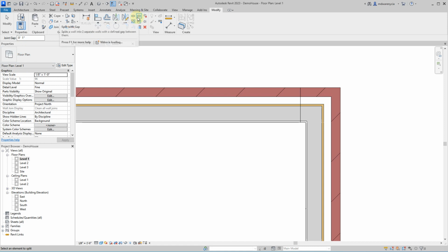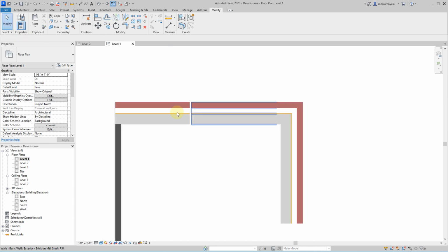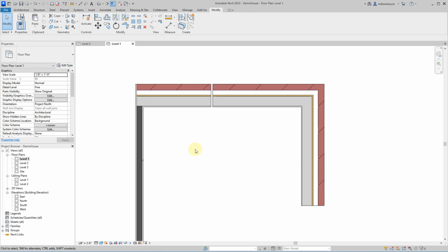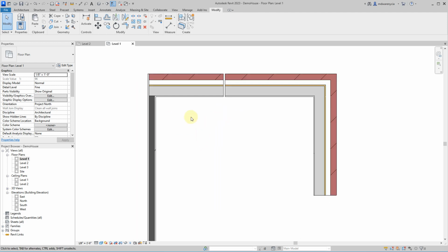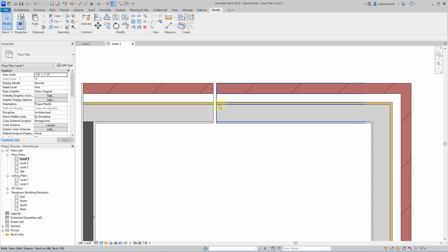So you guys should have all used that one, but some of you accidentally clicked on this one, which is the split with gap. You can right there, split with gap, and it gives you the option to set this gap size. So if I do the cut here, you can see that it actually threw in a 1 inch gap between these and physically separated them. So it works just like the other tool, it's just with the gap. Again, I think this one's more of a hassle than it's worth. But again, it's up to you if you want to use it or not. Feel free to.